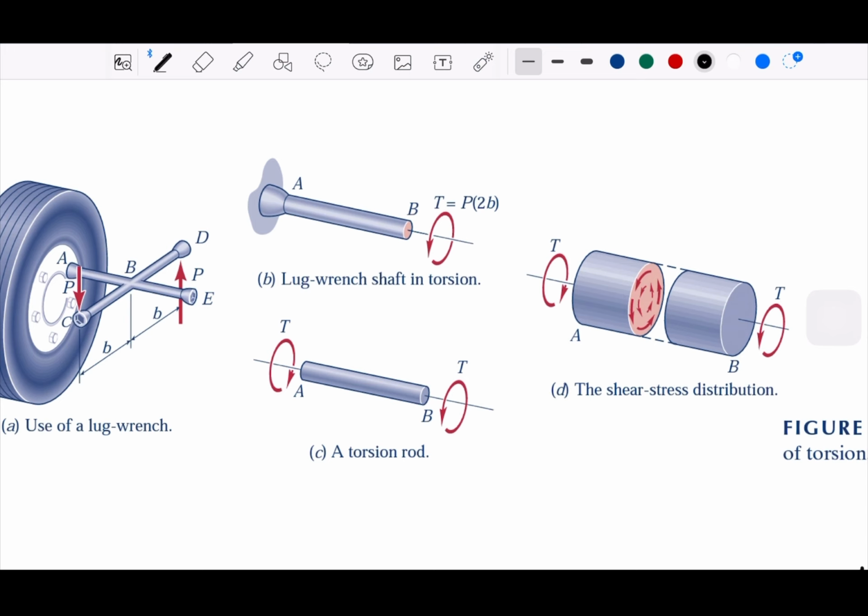And then if we look inside, at the bulk of the rod, if we give the torque, then inside of this rod there will be ongoing shear stress on every member of the rod. There will be a shear stress going inside, the internal shear stress. And that is also important